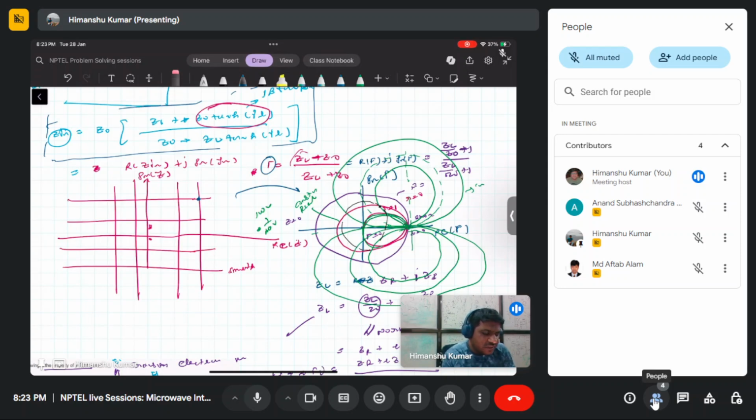But there is a concept called the Smith chart, which is a plot of the real part of the reflection coefficient against the imaginary part of the reflection coefficient. You can map all the impedances in the Z plane to the reflection coefficient plane by this bilinear transformation, and all your correct impedances will lie within this circle.